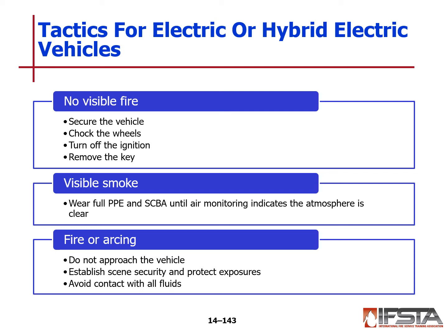Dealing with vehicle fires of this nature, a lot of times there's no visible fire, or in the case that there's not, we want to secure the vehicle. These are the vehicles we want to chock the wheels, turn off the ignition, or remove the key or the key fob from the area.